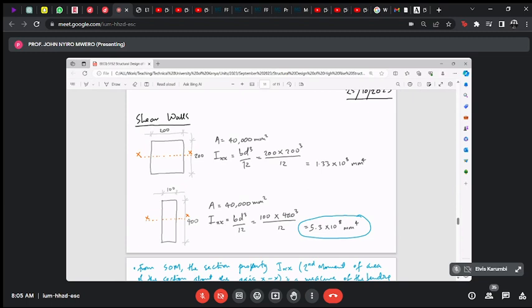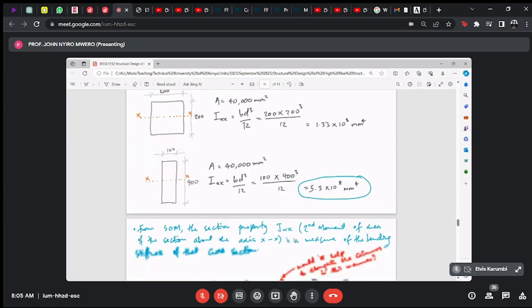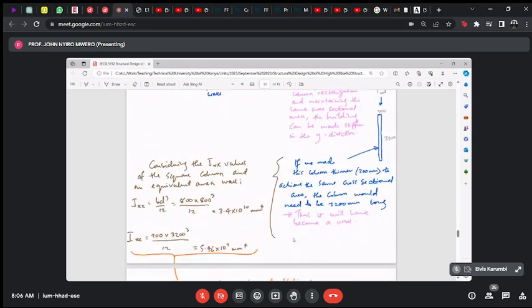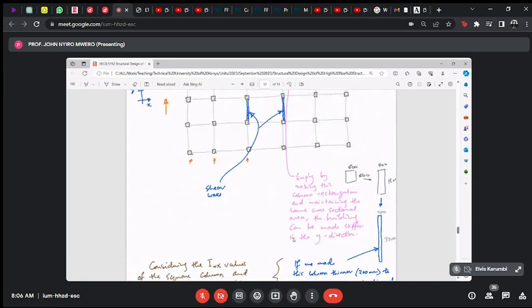We saw that the shear wall basically is an element that is very stiff in a particular direction, not necessarily because it has a larger cross-sectional area, but because of the way the material is arranged. So we looked at this illustration of a square versus rectangular element, and we pushed that thought a bit further to say, now if the column we are looking at in our hypothetical building, the 800 by 800, were to be rearranged into 200 by 200, then it becomes a wall.